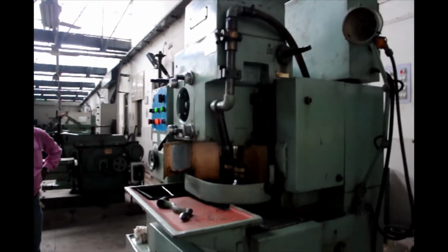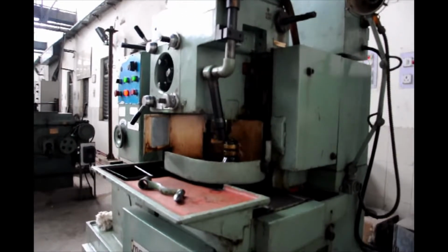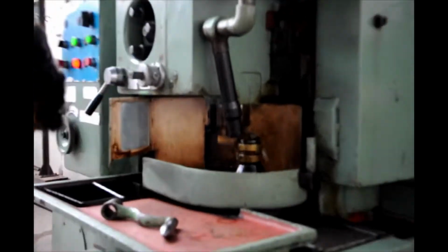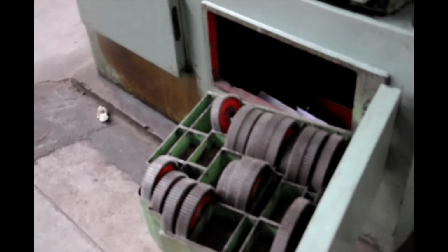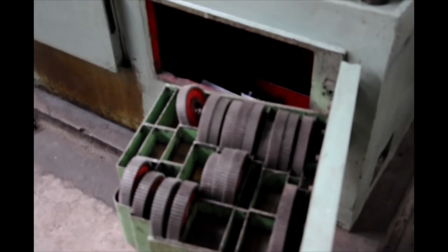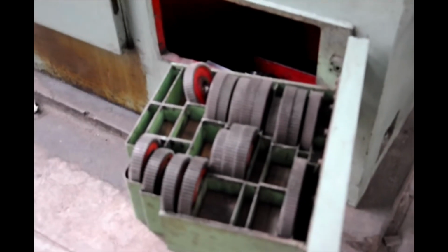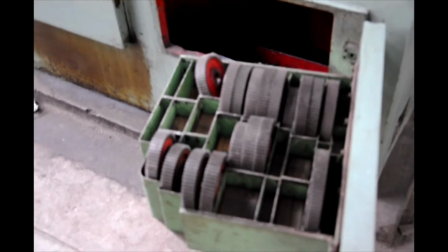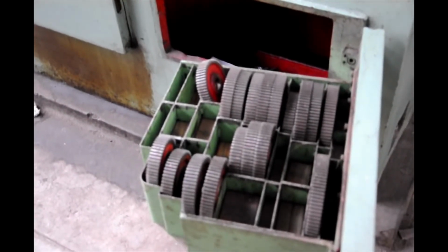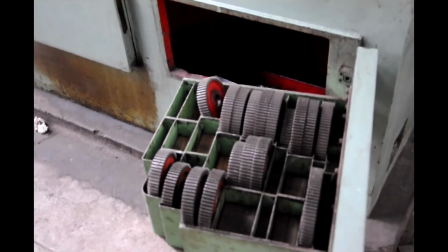The entire implementation of all those tool movements are implemented mechanically. So the gear changing and other part of it, one can see these are the stock of the different kind of gears. These gears are responsible for the different kind of arrangements of all those movements, index movement, because these rotations and other things are very, very important for indexing. And for every definite module of cutting of any gear, definitely there is a gear cutter associated with it.